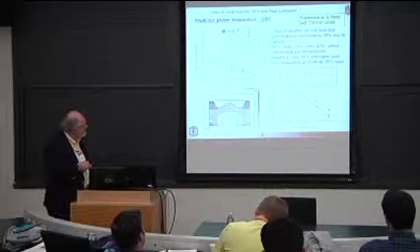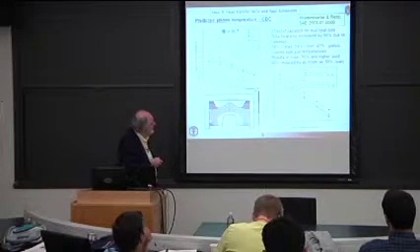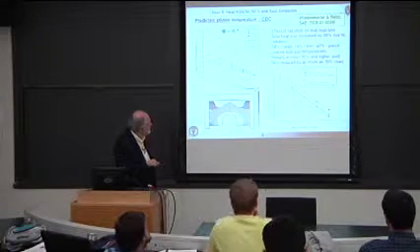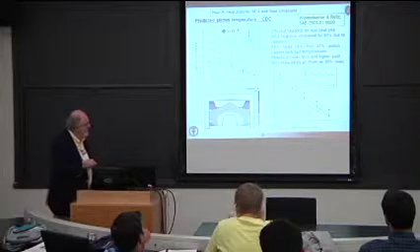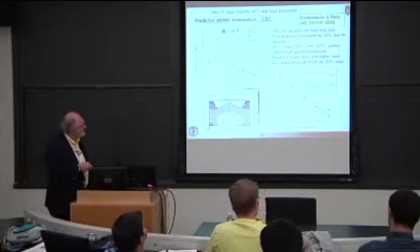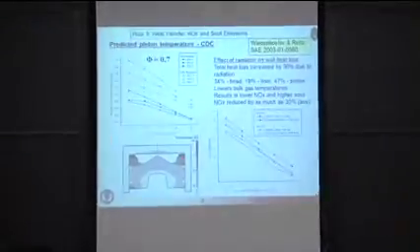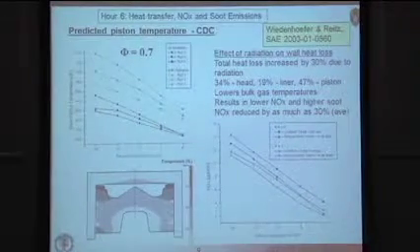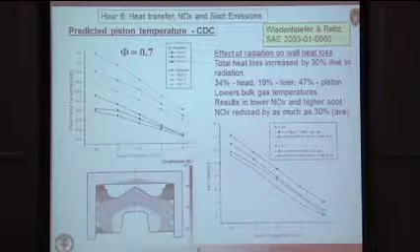It's seen in this plot here, which shows NOx versus injection timing. The cases with radiation are the circles. So that's this one here. So you see lower NOx compared to the open squares here when you have radiation. And this is done for 2 different loads here, the solid symbols and the open symbol. So basically, we see lower NOx, as much as a 30% reduction in NOx, but higher soot in the simulations that he ran.